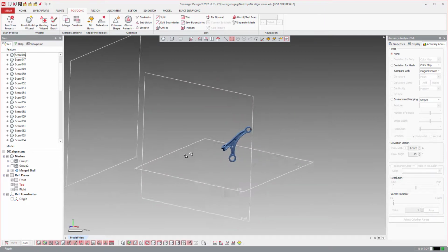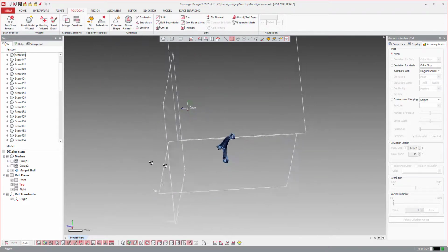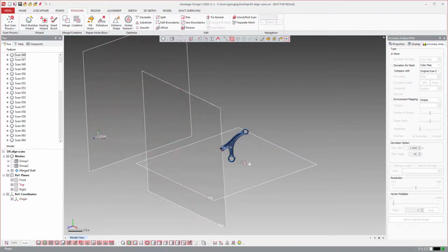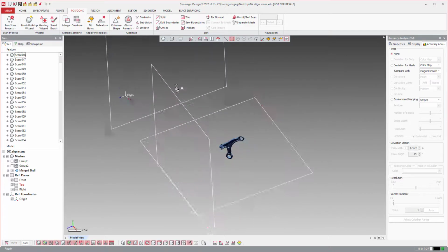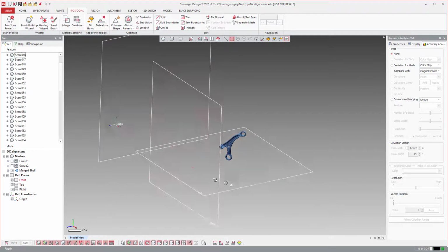And you'll notice that it's floating in a way that the origin over here is where the scanner originally was, and when I scanned it, this is the table that it sat on in the vise, right? So a lot of scanners, the part is actually in an orientation in reference to its zero, and that's usually the way it works. And then what we're going to do is move this in a logical way over to the coordinate system there. That way, when you model it, it's actually in an area that makes sense, that you can do something with, right?